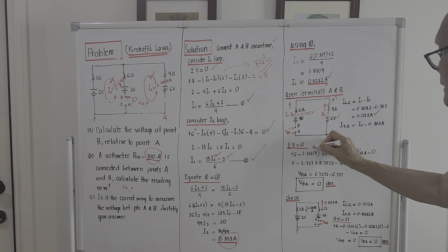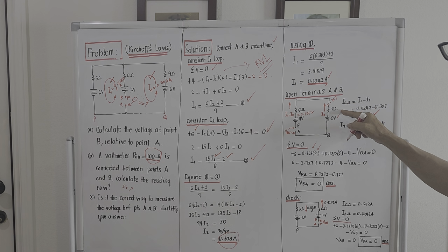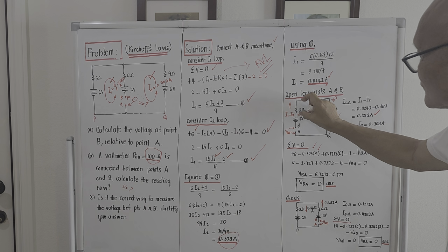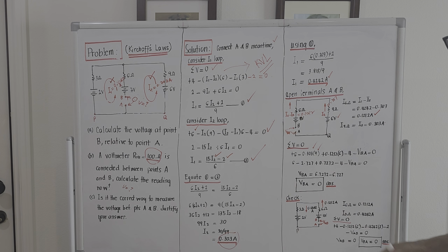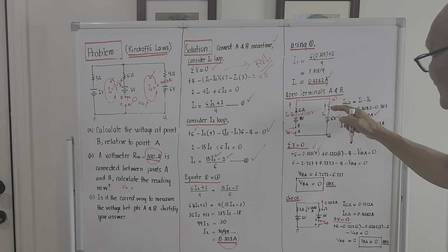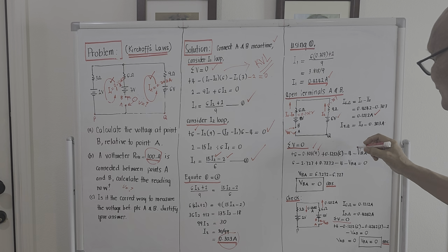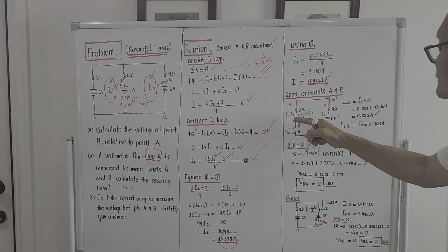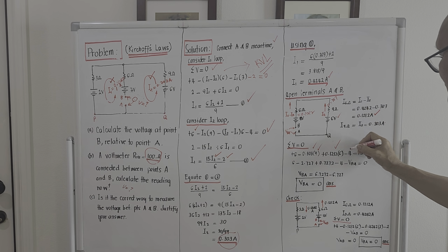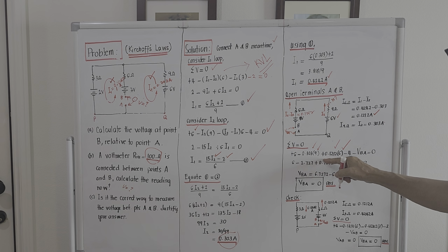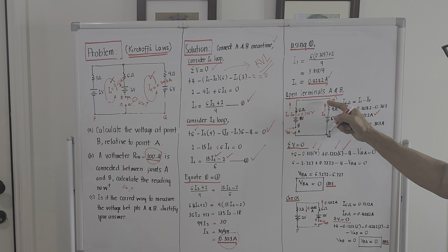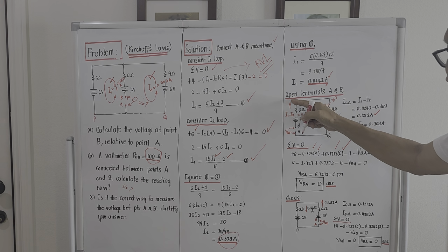It's 0.303 multiplied by 9. Okay? It's a drop. The drop across the 6 ohm load here, it's not a drop. It should be a voltage rise. Why? Because this current here is against this one, right? So this is 0.1212 multiplied by 6. Okay? That's the reason why this is plus. This current is against this one, so if this is minus, this should be plus.